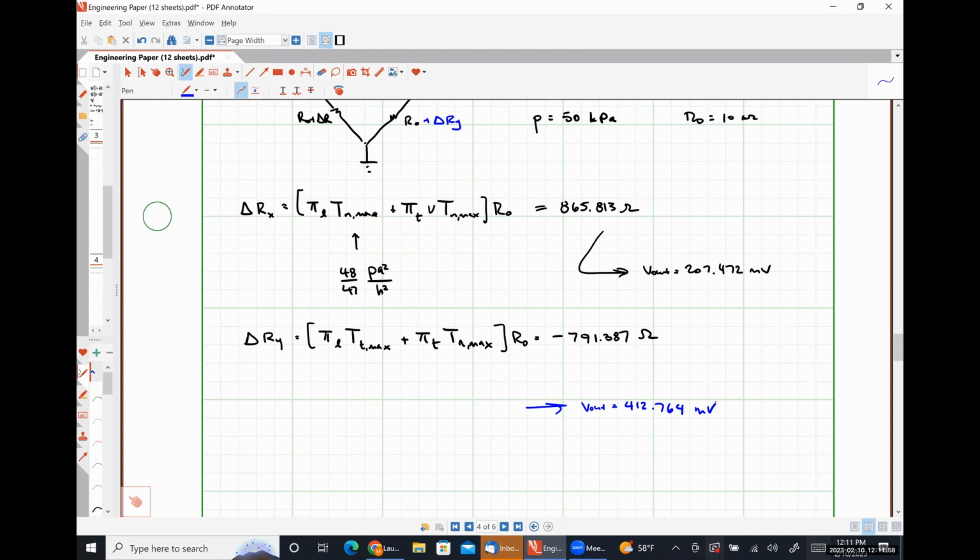Will the accuracy go down marginally? If we didn't have something extra. Why? So the temperature sensitivity is going to still go away because we're using a double-ended ratiometric sensing. So any temperature-based effects are still going to cancel each other out to the first order because of our Wheatstone bridge, actually because of the voltage divider situation.